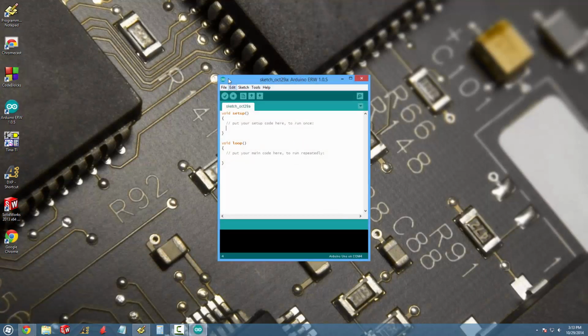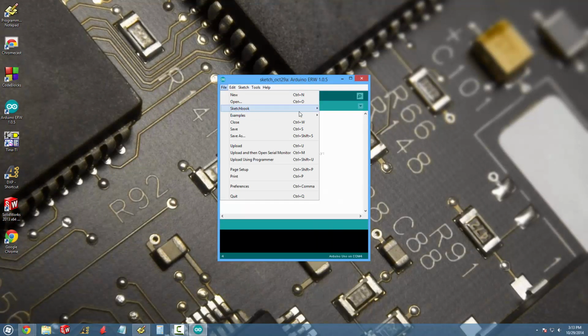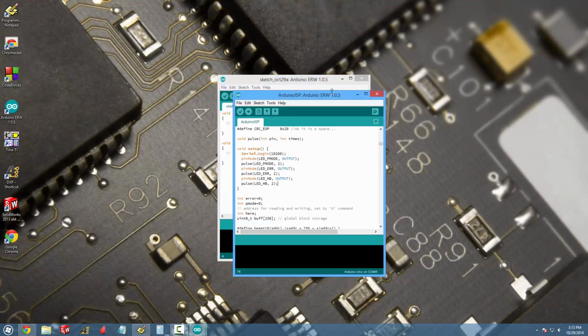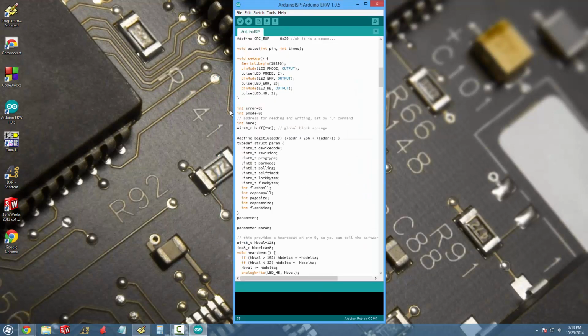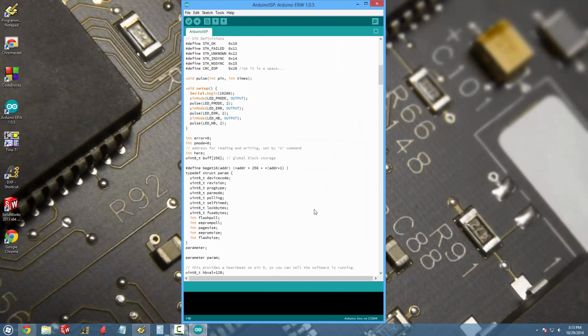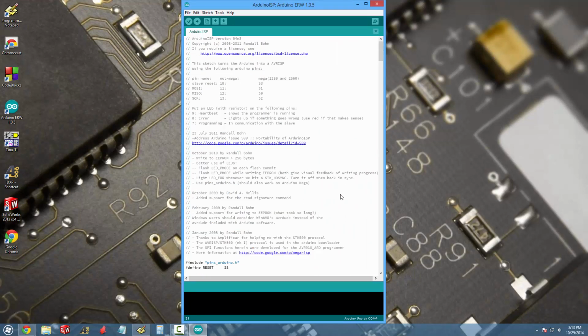If you open up the Arduino IDE and you go into the examples, you'll see a sketch called ArduinoISP. And this sketch here allows you to program AVRs directly rather than using the serial port. Some of you may know this already. When you buy a chip directly from, say, DigiKey or eBay or straight from Atmel, the chips don't come pre-programmed in order for you to upload over USB. You have to use this thing called a bootloader, and this sketch here will allow you to do that.